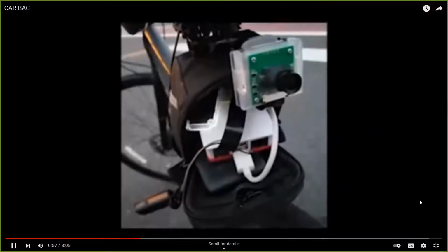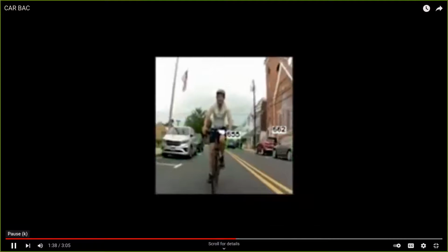And now I will take just a minute to go deeper into the tech and explain how this device works its magic. The cars are detected using an algorithm called SSDLite, which utilizes a deep neural network called a single-shot detector that is run on the Google Coral using TensorFlow Lite. SSDLite generates bounding boxes around all detected objects, which you see as green or red outlines in the video. There are a total of 80 different object labels in the COCO dataset that the model was trained on, but we are only concerned with a few, such as cars, trucks, and motorcycles. So we simply ignore any objects detected that do not fall in these classes.